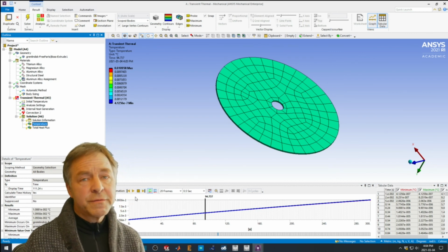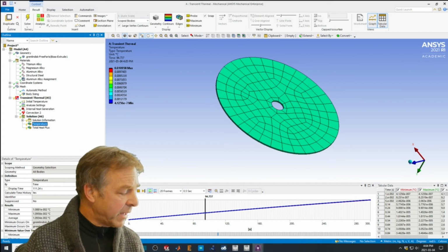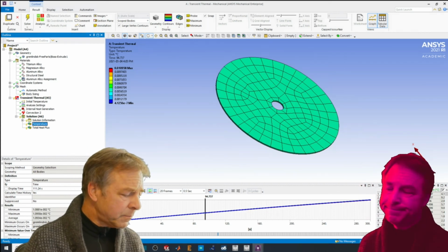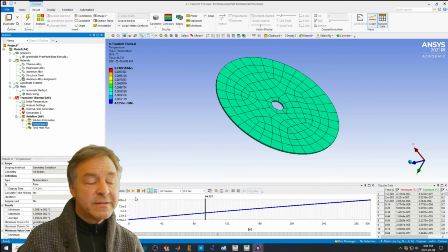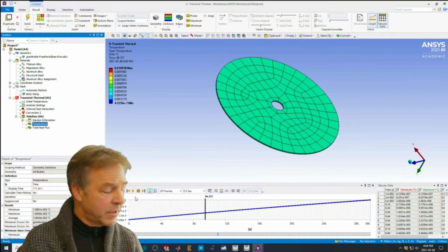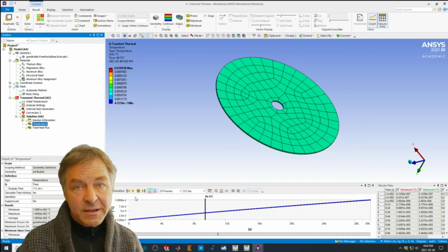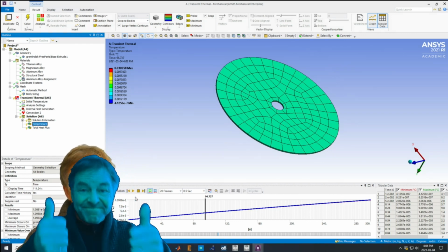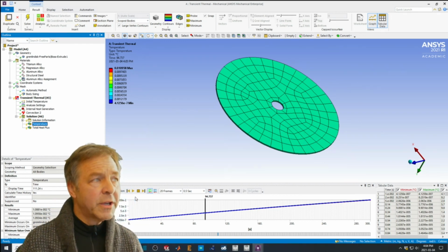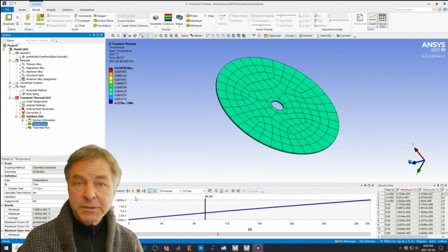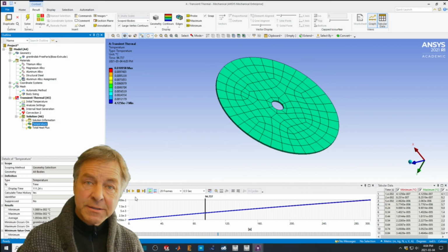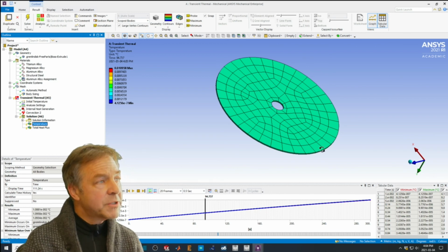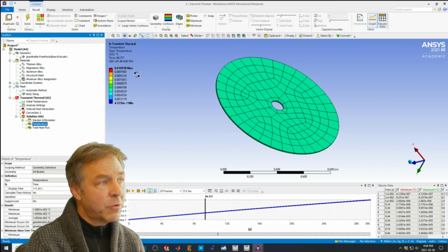Now, we could have refined the calculation we did by hand and looked at how long it might take to get to 0.05. But in our unsteady calculation for 300 seconds, just by hand, simple calculation, we got an answer of 0.012 degrees C as the temperature difference. And look what our simulation showed, 0.011.